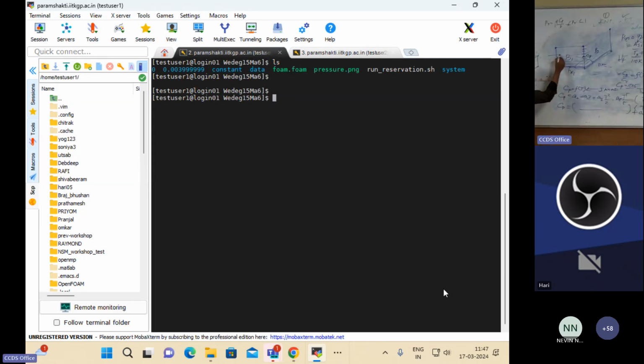And typically for the boundary condition, this is pressure, velocity, and temperature. It is fixed at free stream conditions. This is far field. This is outlet. And these two boundaries are walls. That is, it is no slip and zero gradient temperature. That is isothermal. Adiabatic wall. These are the typical boundary conditions for solving this type of problem.